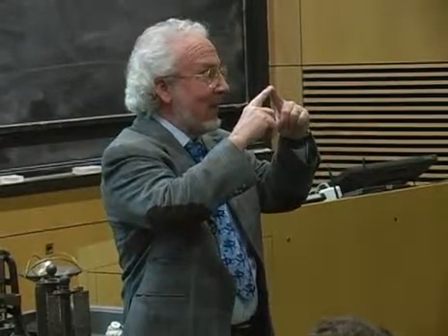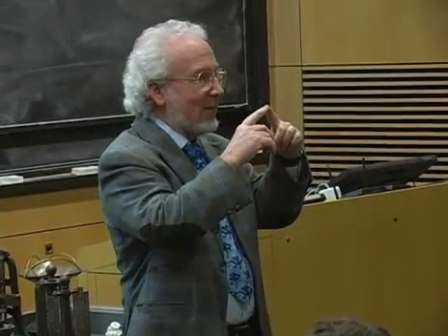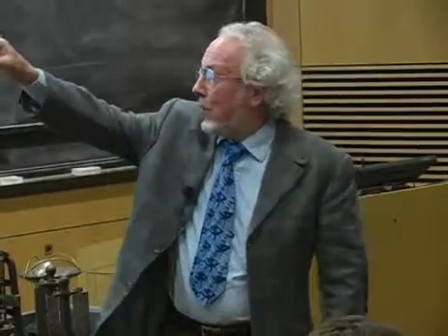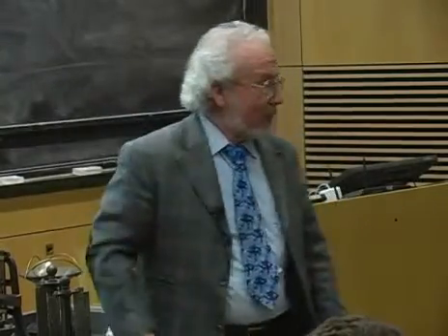Okay. How many degrees of freedom does it have if I fix one of the links? None. So if you put in n equal to 3, right, and you put in 3 joints, you find that the number of degrees of freedom is 0. Okay?